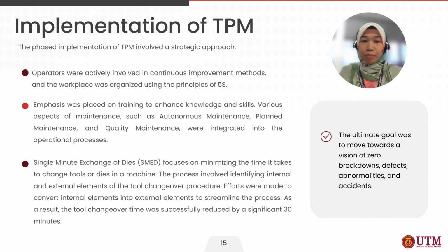Concurrently, SMED steps in to address the prolonged tool changeover times. The methodology entails breaking down the internal and external elements within the tool changeover procedure. The main objective is to streamline this process and convert internal elements into external elements, which effectively reduces the tool changeover time by a significant 30 minutes.